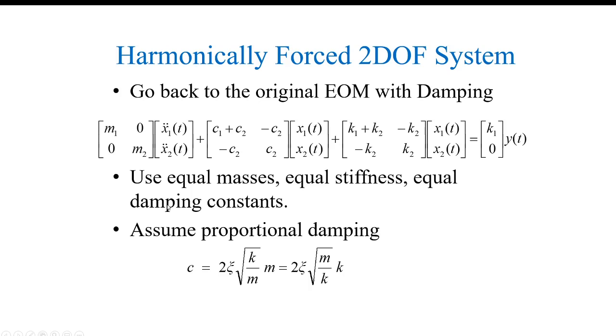So now going back to the harmonically forced system response. This is not technically a forced system. You have a prescribed input motion. The input is a motion, not a force. So now going back to the original equation of motion, what I want to do is find how the response varies as I change the base motion. The base motion will be a harmonic with a given amplitude and the frequency that I decide.